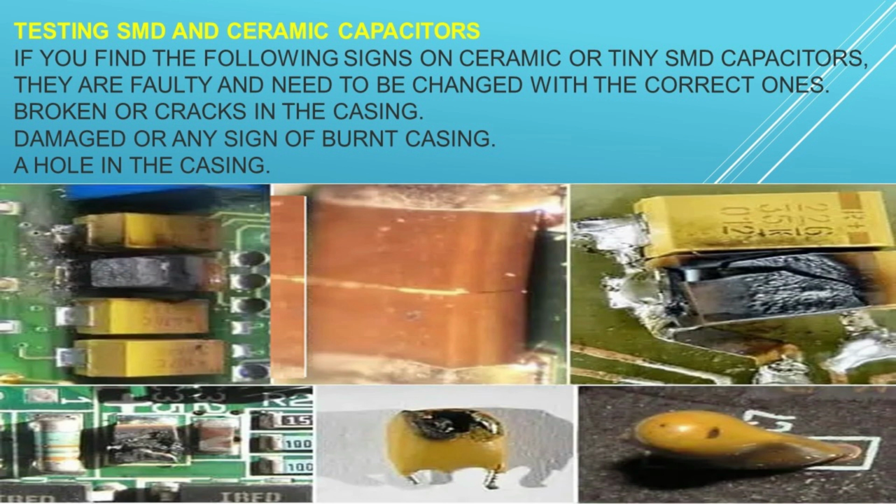If the multimeter doesn't show a continuity sign with beep or LED, it means the capacitor is open. If the multimeter LED lights on and makes a continuous beep sound, it means the capacitor is short and it should be replaced with a new one.